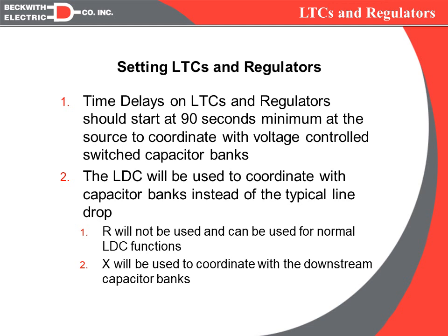So whenever you're coordinating LTCs and regulators with capacitor banks, you always want to allow enough time for the capacitor banks to operate first. So therefore, we recommend stretching out the time delays and having a minimum setting of 90 seconds. I know some utilities that go 180 seconds on their time delays at the LTCs. The advantage being that we will have more capacitor bank operations and fewer LTC operations, and also have a better overall power factor.